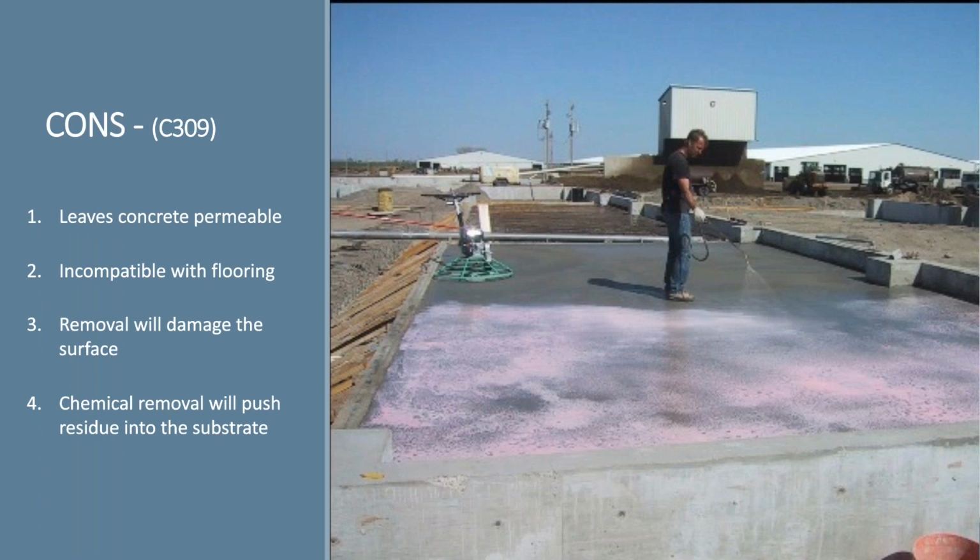One of the things I should have commented on my ASTM warning site: ASTM C309 and C1315 are specifications designed around controlling a single element of concrete curing, and that's moisture loss. The test method, C156, only measures the rate at which water or moisture leaves the concrete, and it sets the maximum loss rate at 0.55 kilograms per meter squared. C1315 is 0.40. Anything below a 0.40 is an improvement.